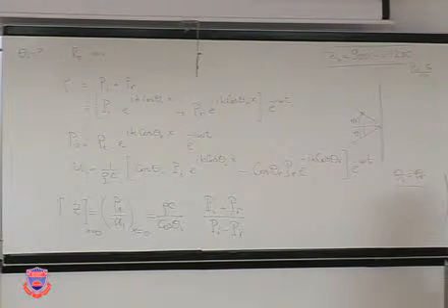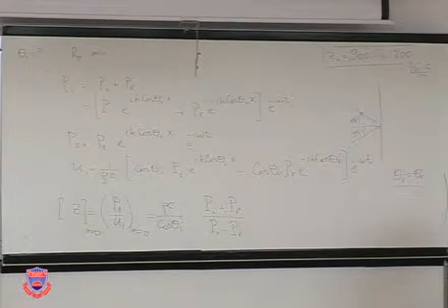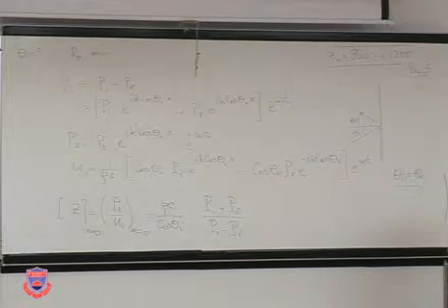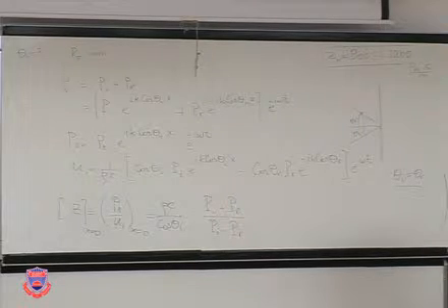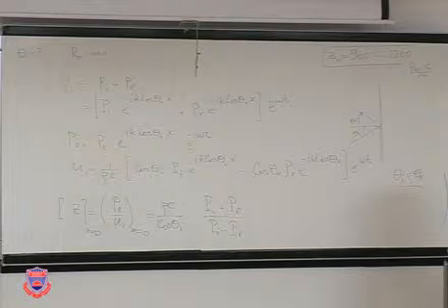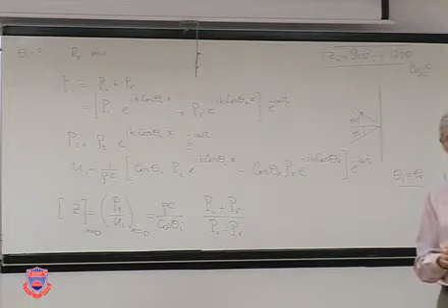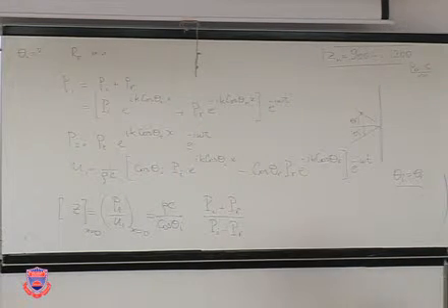Actually, rather than deriving these equations, you have supplied us an equation in terms of normalized impedance, reflection coefficient. I use this equation, but here the question is how am I going to use the complex impedance? Do I need to use the real part, or do I need to find the magnitude of the impedance? I found the magnitude of the impedance on the surface, and I substitute the value into the reflection coefficient equation.